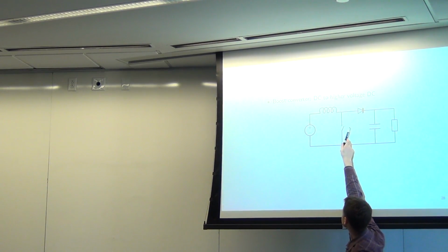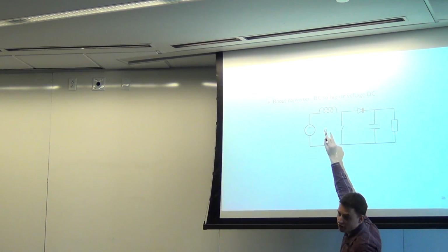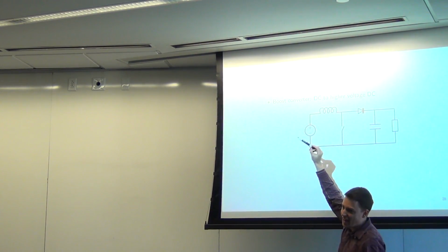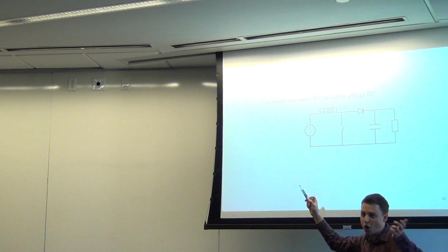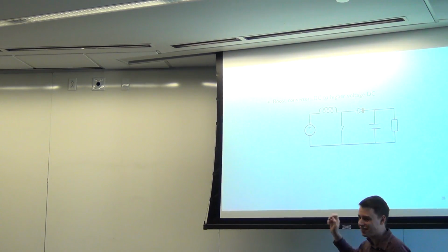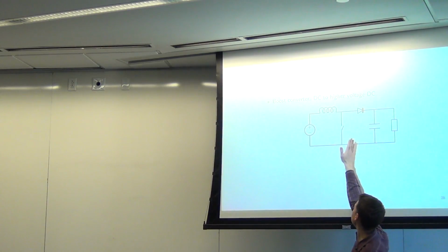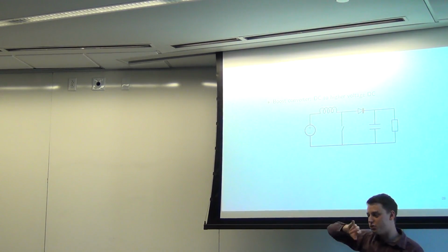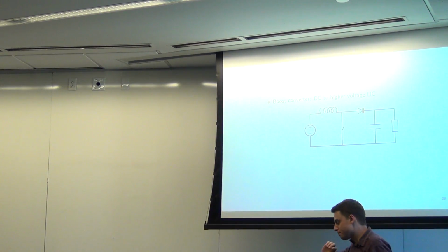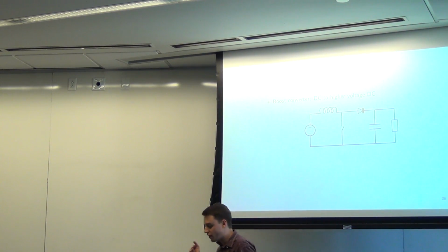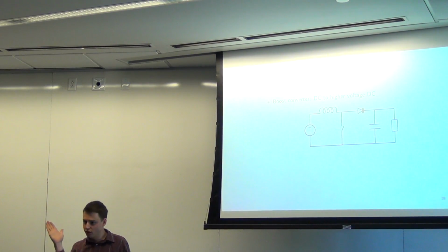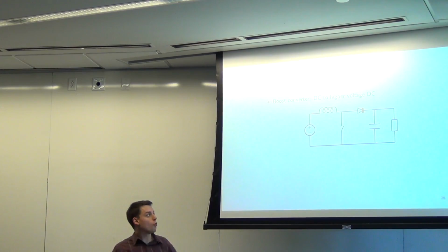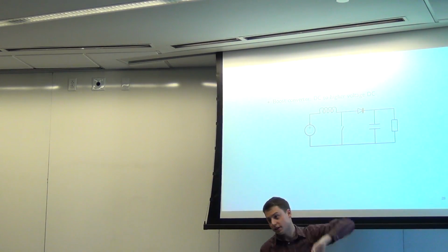So here now, if the switch is closed, there'll be a short circuit here. So current will just keep building up more and more through this thing, right? So actually, nothing really happens if the circuit's always closed. But at least in theory, you can imagine that current is going to keep going up and up. And when you open it, then it'll put a very high voltage across that. So the idea is, the closer you get to having it always closed, the closer you'll get to a very, very high voltage. And if it's always open, of course, it'll just have the same voltage as the source.